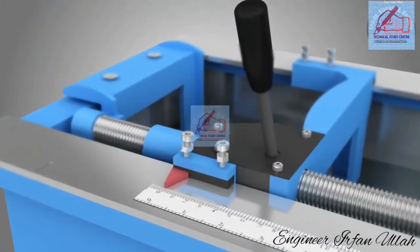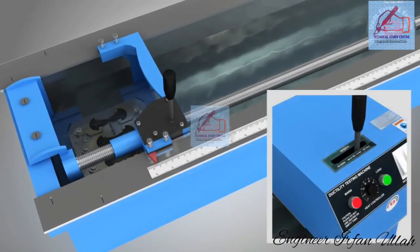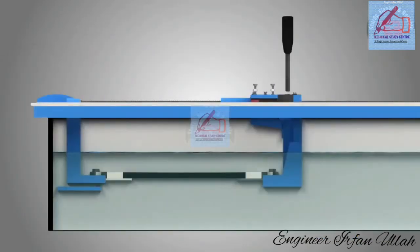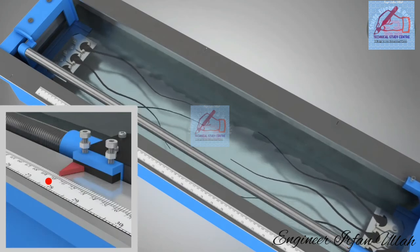Pointer is set to 0 and the machine is started, and 2 clips are pulled apart at the rate of 50 mm per minute. The sample is immersed in water at least 25 mm above and below while performing the test. The distance at which the bitumen thread of each specimen ruptures is recorded as the ductility value in centimeters.